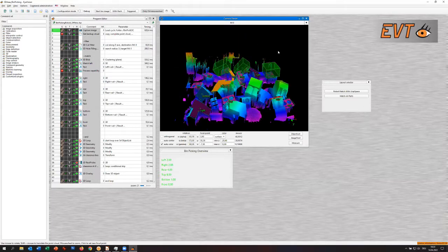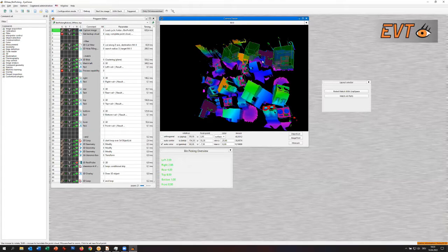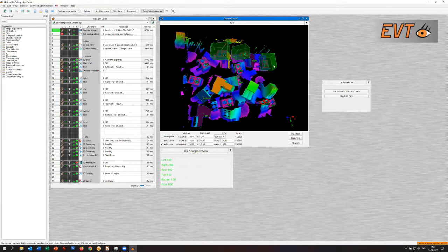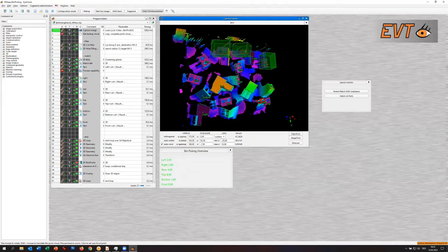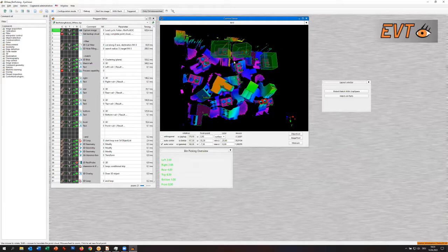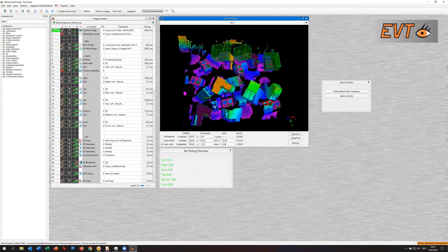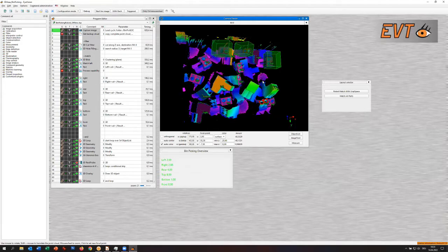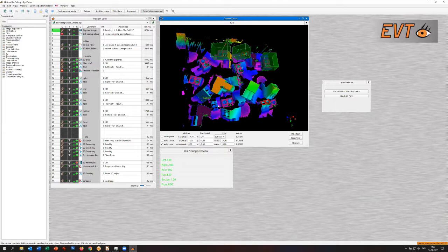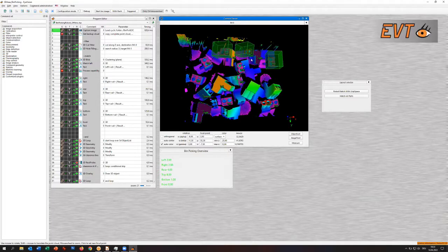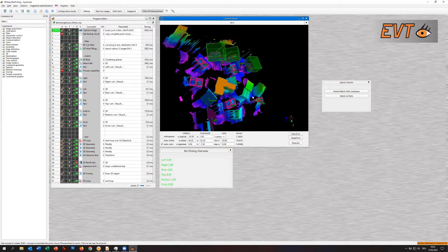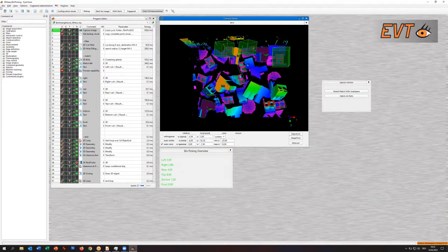The boxes on top in this case are the free space above the parts to pick it with the robot. So you see, we find a lot of these parts, but first of all, we cannot pick all with this robot, and some of them cannot be picked because there is not enough space, for whatever reason, based on the definition of the minimum space to pick it with the gripper.